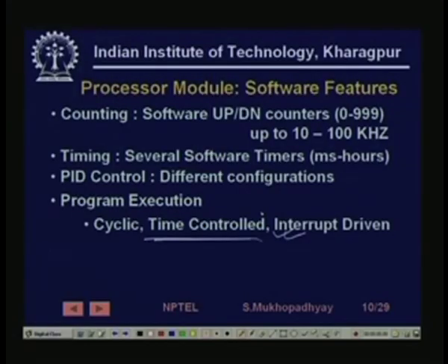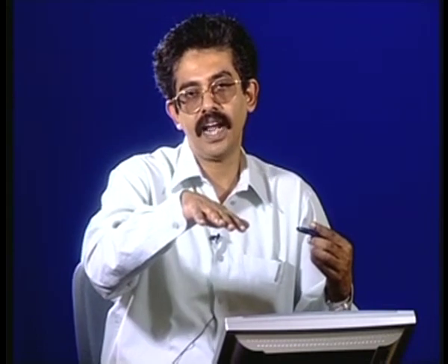There are some tasks which can suddenly occur, like failures, which once they occur are not taken into consideration of the regular computing flow, but once they occur they are required to have very high priority, and therefore they have to immediately get the attention of the processor. So such tasks are sometimes coded in the interrupt driven execution mode. So whatever the processor was doing, it will be interrupted, and this requirement will be catered to.